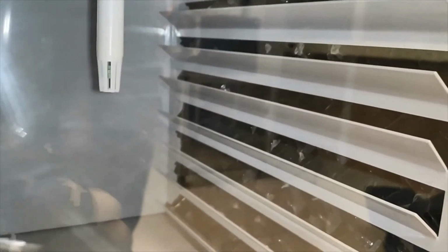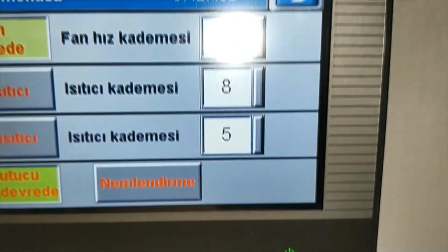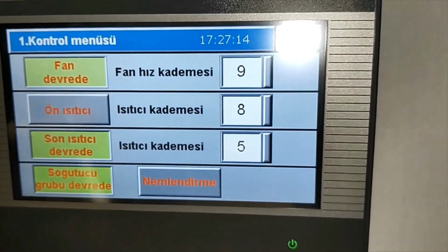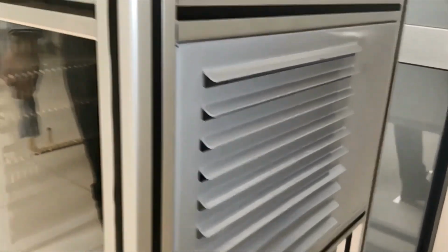In this section, the humidifier can be seen, but it is closed. The air continues to move to the after heater after leaving the cooler. With switching on after heater, the air reaches the desired level temperature which we want, and after passing the after heater, the air leaves the setup from these channels.